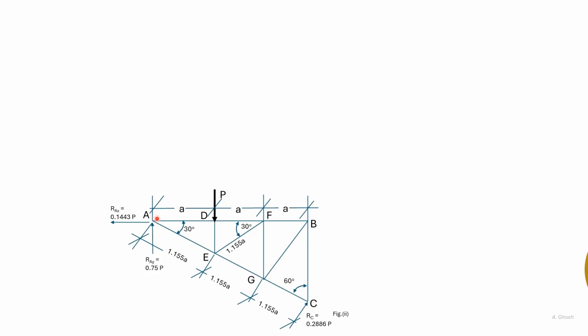We found that the force due to AE acts out of A and the force due to AD acts towards A. Now the joint A will react with equal and opposite forces.